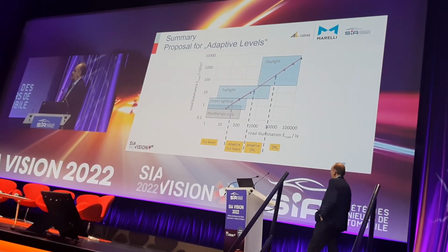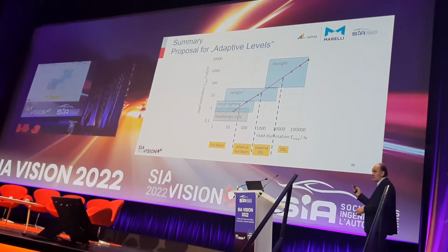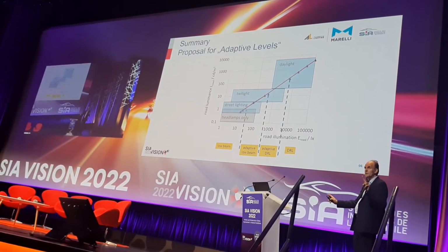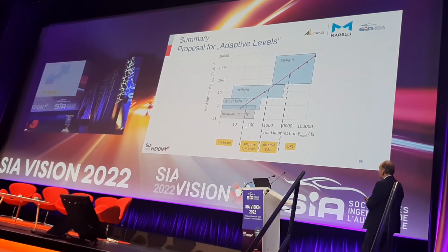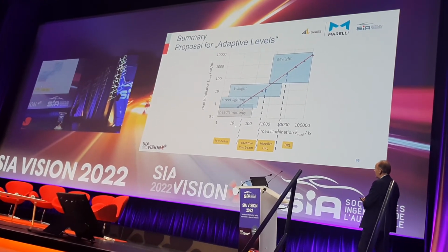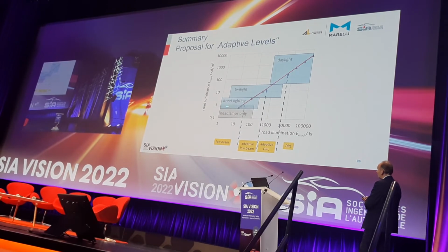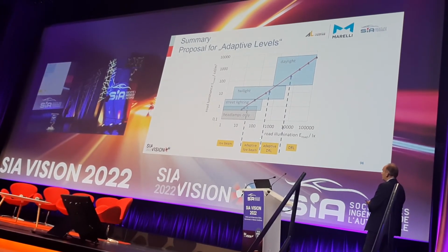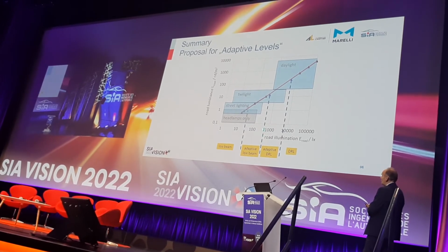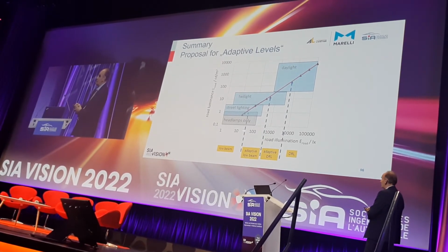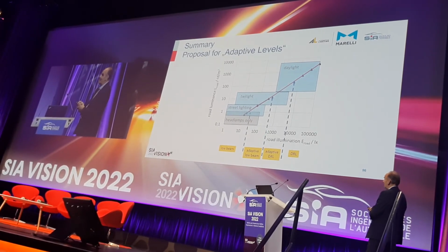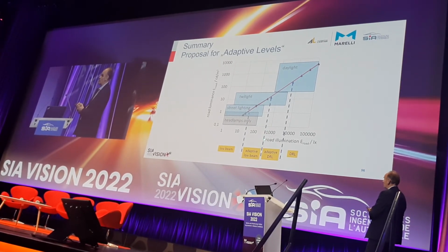Summary on the last slide. Today we are driving low beam or DRL, only two lighting functions. To have a more intelligent split, we use the low beam for low illumination levels, with an adaptive low beam balancing range and the full flux portfolio of the low beam up to 500 lux on the road.